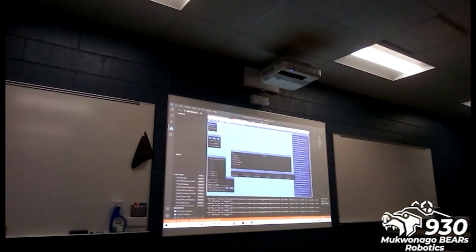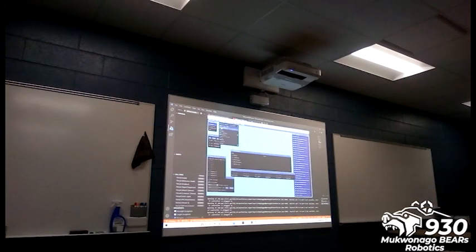Oh, you still have to do the breakpoints. So first, if you go into this hardware tab, you can get a lot more of your inputs, like the DIOs, which are our sensors. So we want to turn these all to low first so that they aren't detecting anything. We aren't using the first four right now, but we would still want to turn those to low so that they aren't affecting anything. And then these two DIOs, 5 and 6, are the ones that we'll be using.